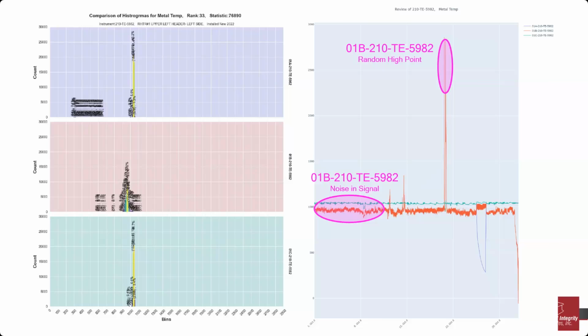But for some reason, the way the control logic is set up, when we get into these really low load operations, the unit Charlie hot reheat bypass pressure control valve wants to pop open and spray into the system when obviously it's not needed. The system's still online. Bypass valves are really designed for startups and shutdowns and unit trips and things like that. So it should not be opening during normal operation.